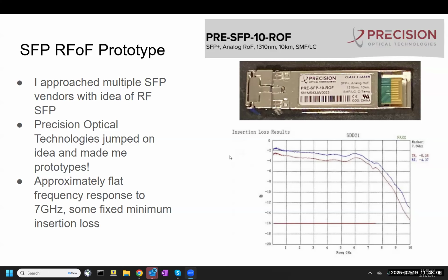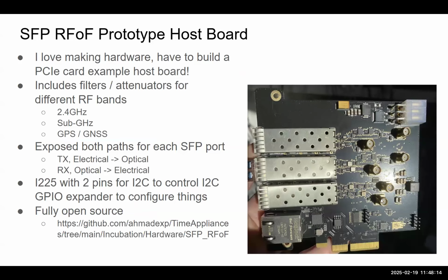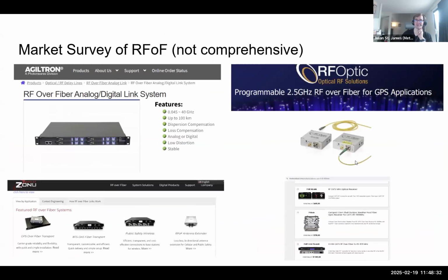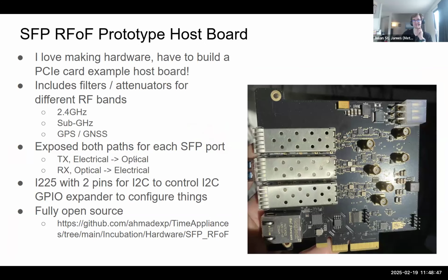So now we need a tap card without RF connectors, just with fiber connectors. Just SFP cages, yeah. I could. That's why I built this as a standalone distribution card, but that would definitely be possible now. I would just have to think about what to put on it. This is limited by the PCIe faceplate, but if you were to build an appliance, something similar to these boxes, it could look almost like a normal network switch with a bunch of SFP ports and coax ports. But it would all be SFP over fiber ports.